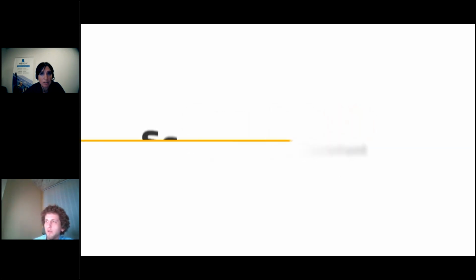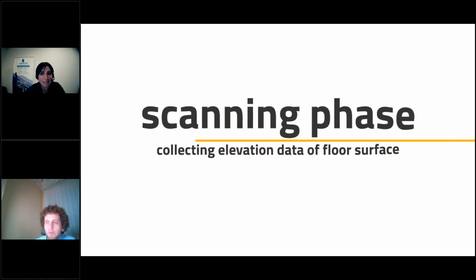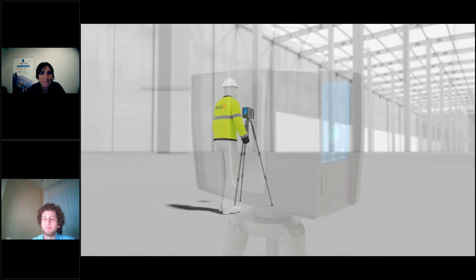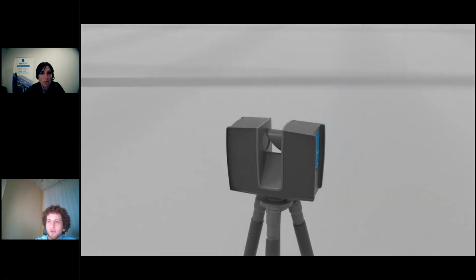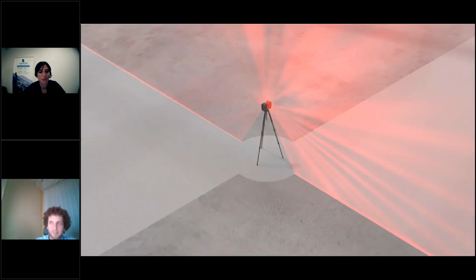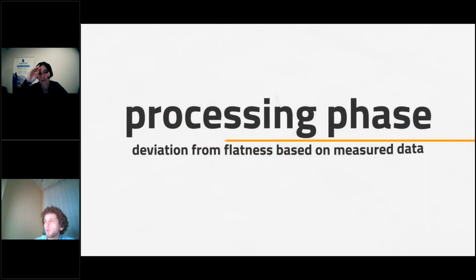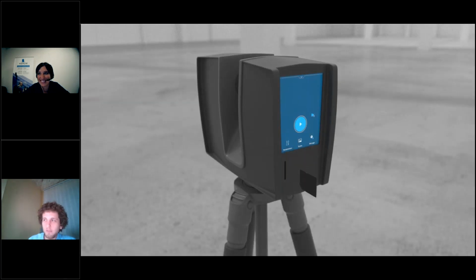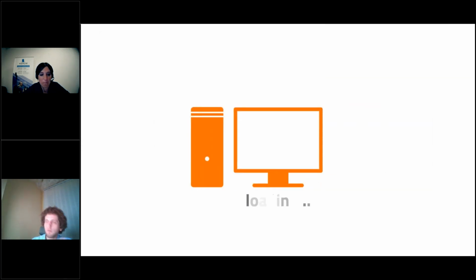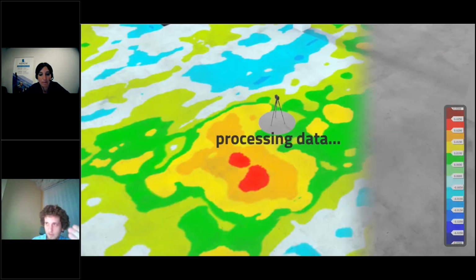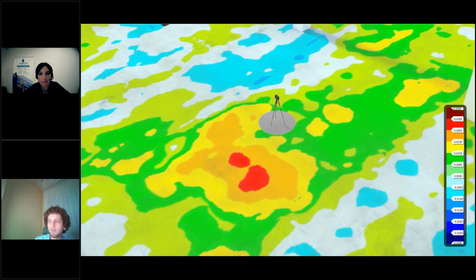Exactly. So we have our own little introductory video about this whole industrial floor, just to show what to do and what happens within the site. So, well, you can recognize quite well which model we used to create. That's a Faro. We do the scanning for the whole concrete surface. We have to process and extract the proper geometric forms and the data from the raw scan data. We put it into the computer, Faro Scene or like a Cyclone. Then we use Reconstructor, create these elevation maps.